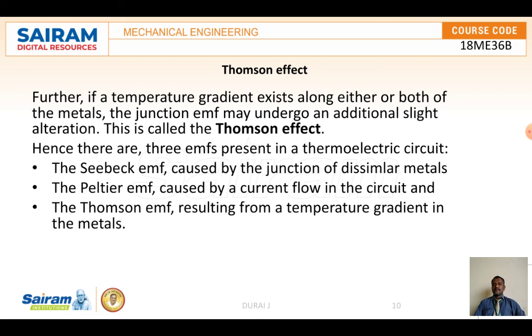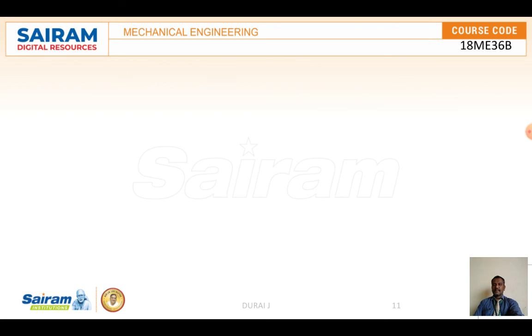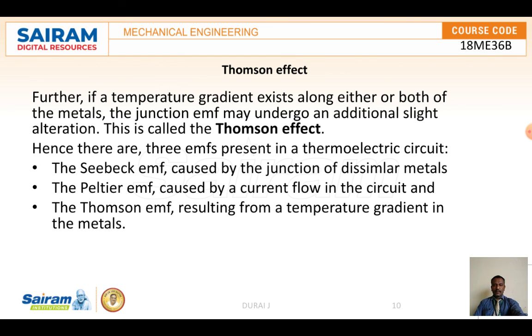Hence there are three EMFs present in the thermoelectric circuit. One is the Seebeck EMF, caused by the junction of dissimilar materials. Another is the Peltier EMF, caused by current flow in the circuit. The third is the Thomson EMF, resulting from the temperature gradient of the metals. So that is about temperature measurement.